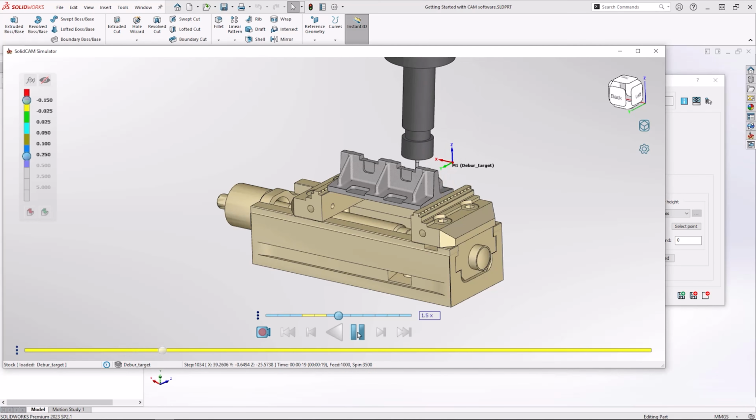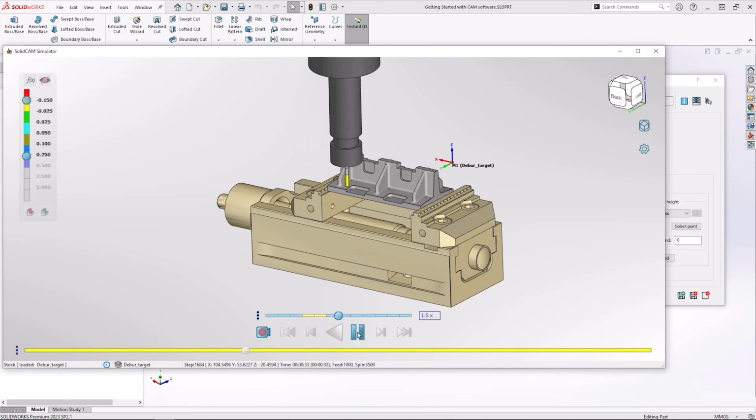You can see it turns the tool in all 5 axes because the machine we're using is capable of this, whilst maintaining it doesn't collide with the stock or the fixture. As we can see, it's gone round, picked out all the edges and done a great job of something straight away. But there is more to this toolpath if we want to define something more specific.